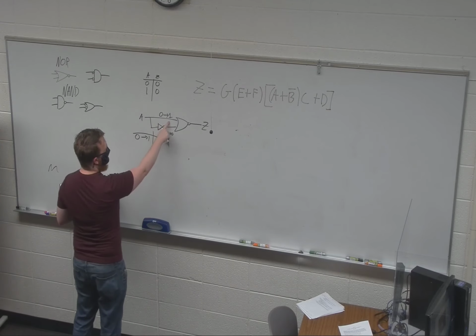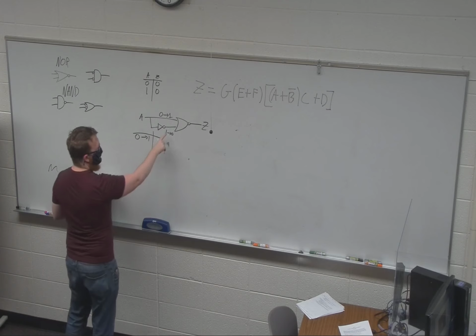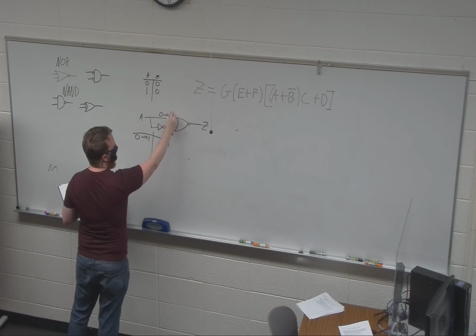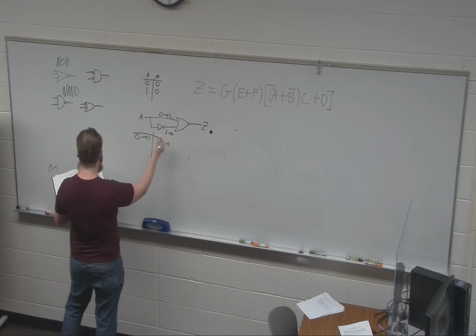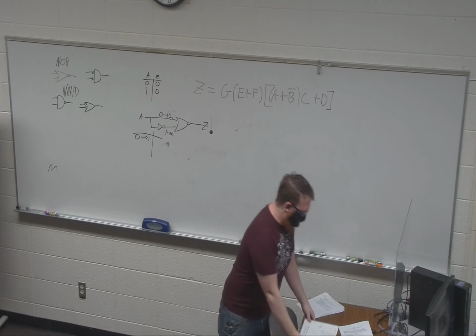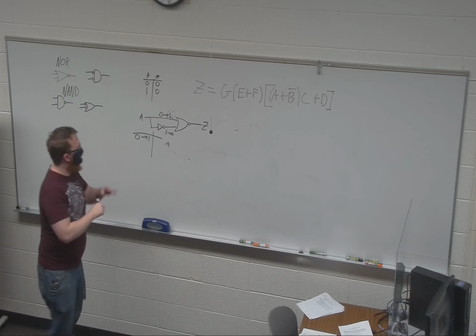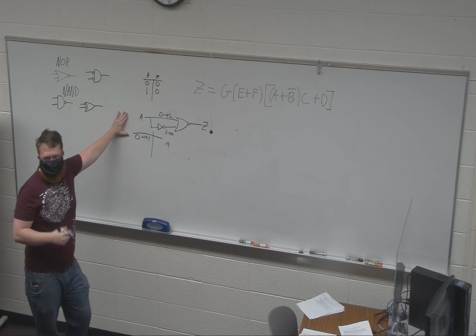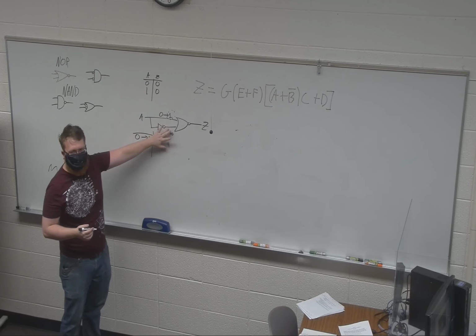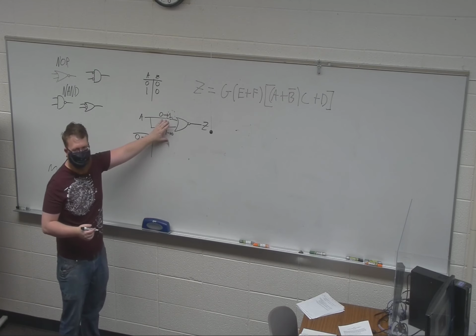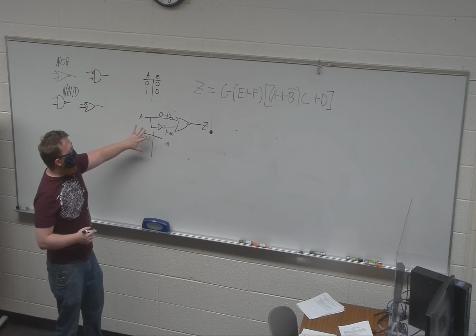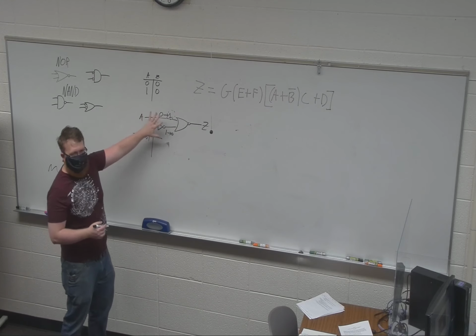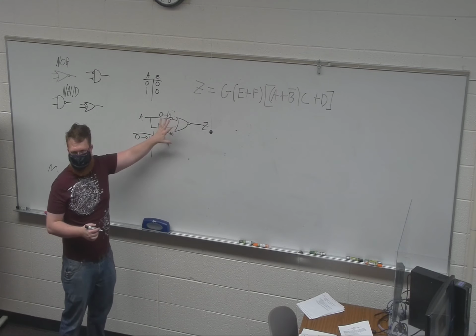So there's going to be a window in time on this one where I have a 1 at this gate and, sorry, I haven't run through this example and my brain's farting. I'm not a morning person. So let's puzzle through. What we're going to end up with is this issue where there's a temporary change, a quick change on this one, a temporary change on this one, and our output's going to end up glitching. And so now it's just a matter of puzzling through why that's going to happen in the timing.